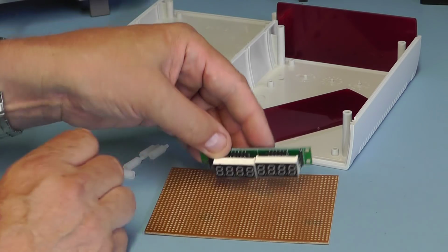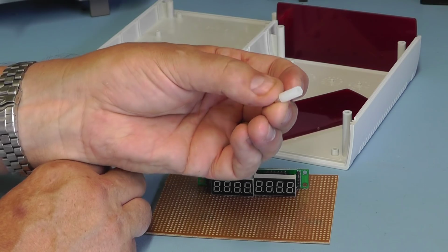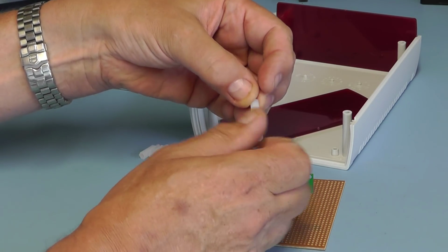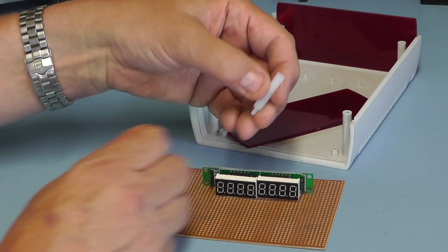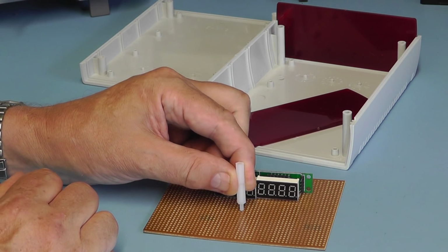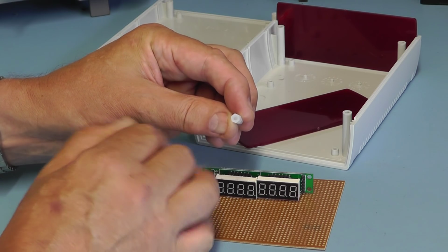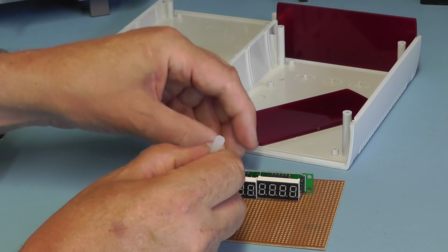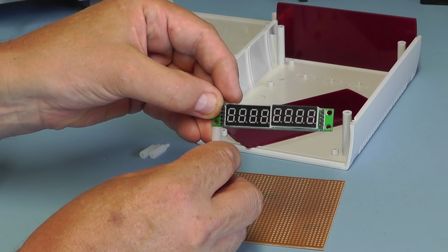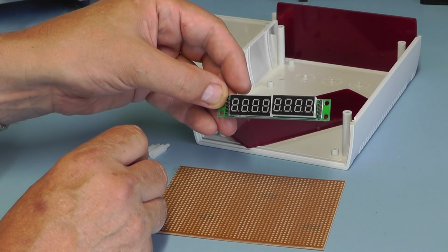And what I've decided to do is use some of these spacers, these hexagonal spacers. I probably need to use 2 of them so I can screw 2 into each other, and then my idea is these will then bolt through onto the matrix board, and then if I cut a slot into the top of these so I can slot them onto the display, then we can support it on the project board. I'll show you that when I do it.